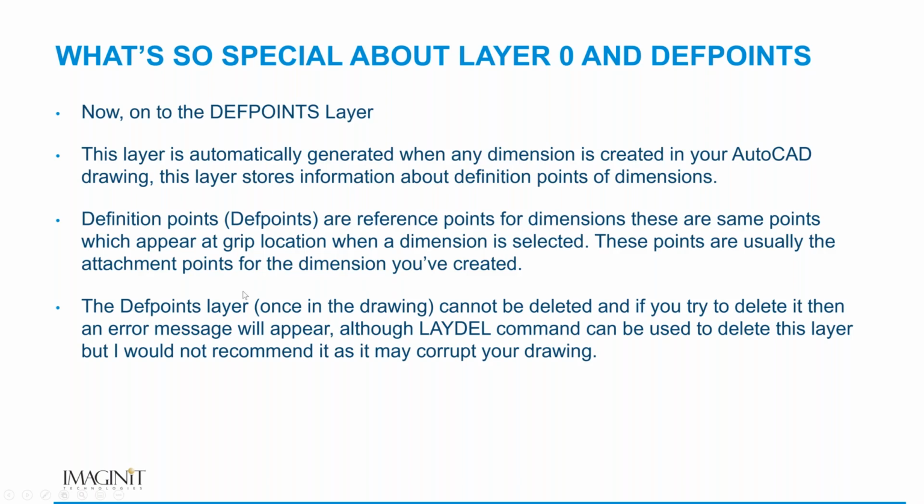The Defpoints layer, once in the drawing, cannot be deleted. If you try to delete it, an error message will appear. The LAYDEL command, or layer delete command, can be used to delete this layer, but I would not recommend it as it will corrupt your drawing.